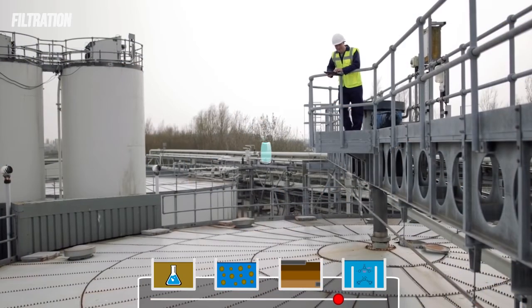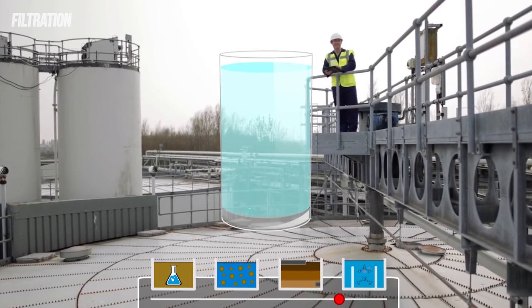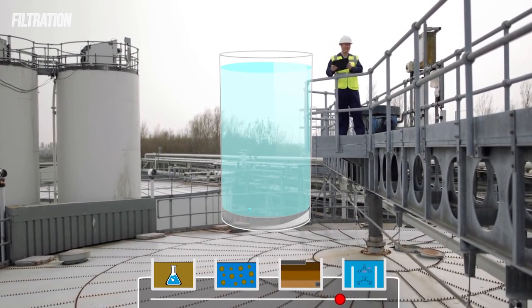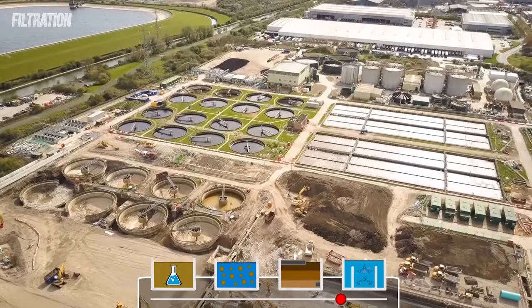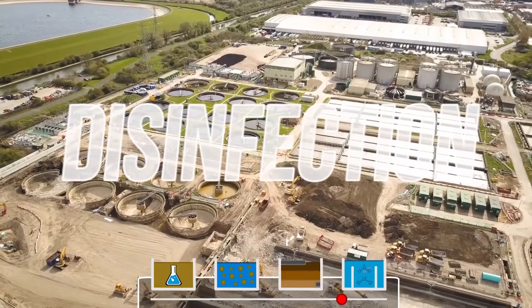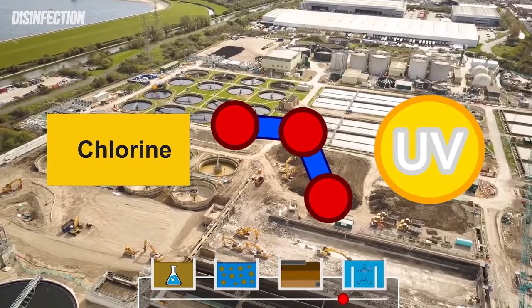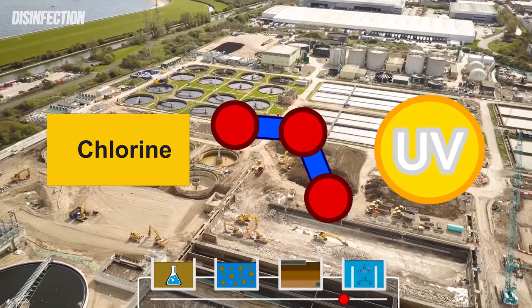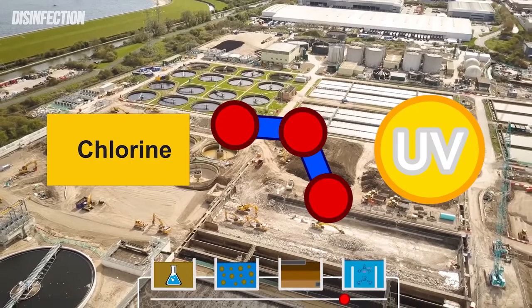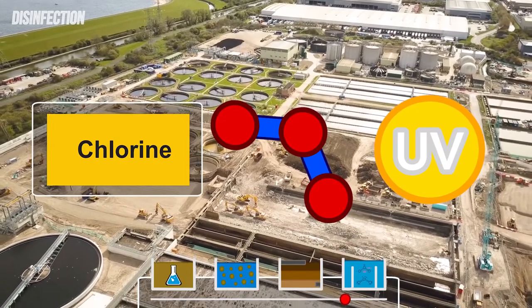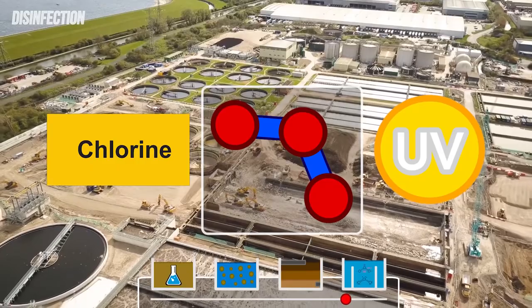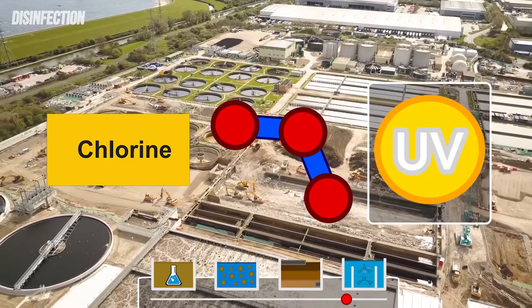At this point, the water should be mostly crystal clear, but there still remains some residual bacteria. That leads us to the next step: disinfection. There are 3 main ways of disinfection in the water treatment process, which can be used individually or in combination with one another, depending upon design. First, chlorine or chloramine treatment, there's ozone treatment, and finally, ultraviolet radiation treatment.